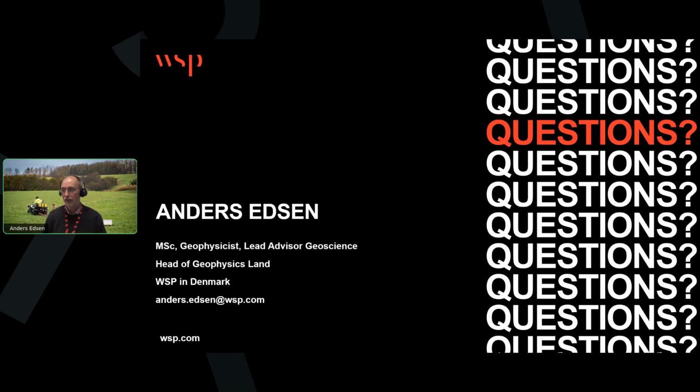ERT methods are very good in distinguishing the whole range of resistivities, but the main reason for employing EM methods is that they are able to map areas. If you have line separation small enough, you could get a 3D picture of your survey area for a significantly lower price than it will take to do the same with ERT.